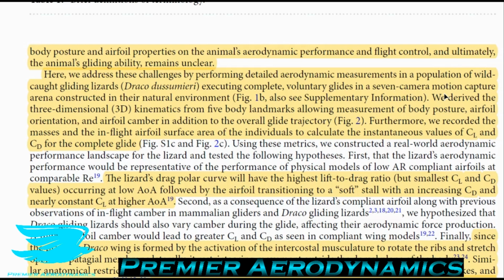The more you tax the flow, the less energetic it becomes, which means the more likely you'll get little parts of the airfoil stalling, so flow separating, and also potentially increasing the induced drag by increasing the lift. So you get a reduced drag at low angles of attack, but you still get pretty decent lift production.